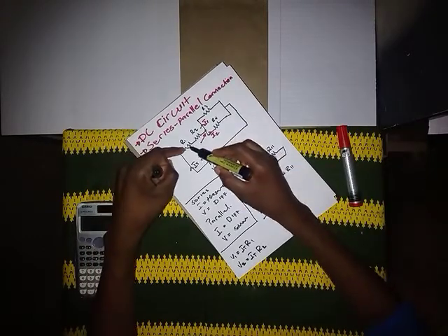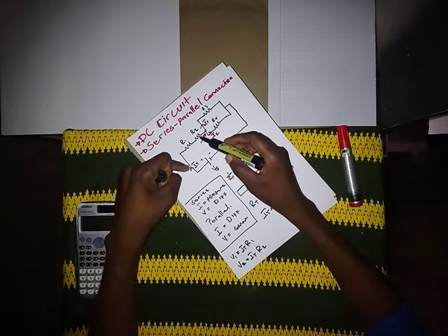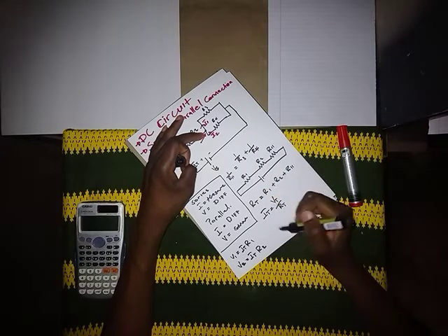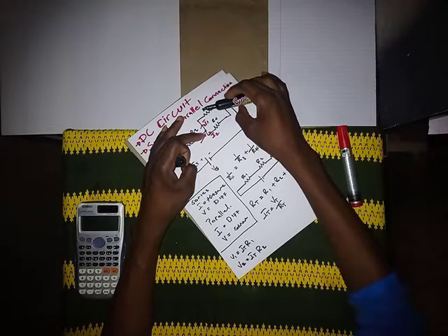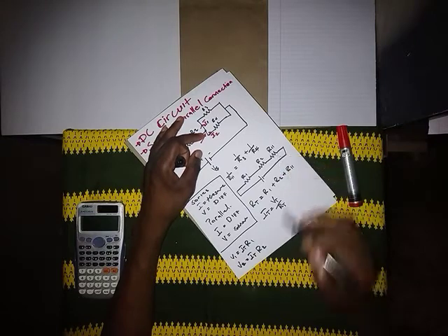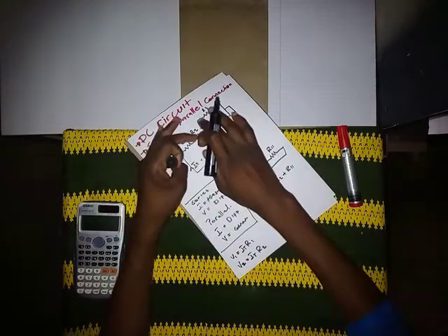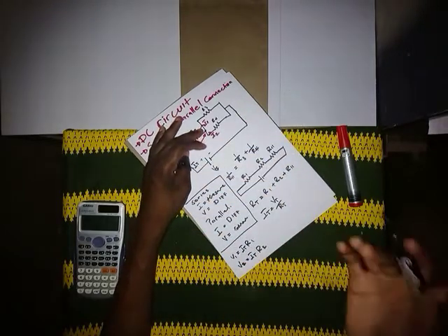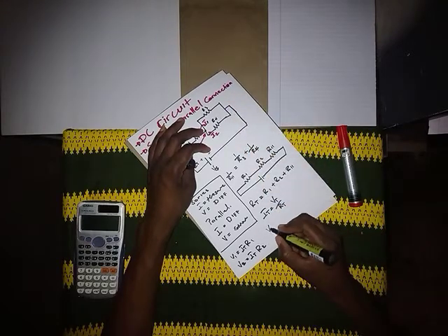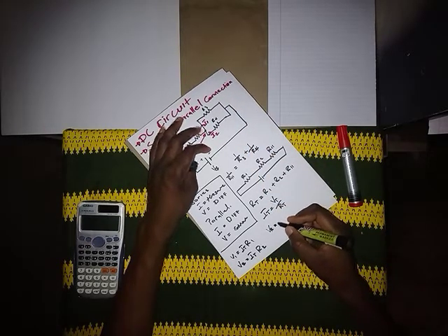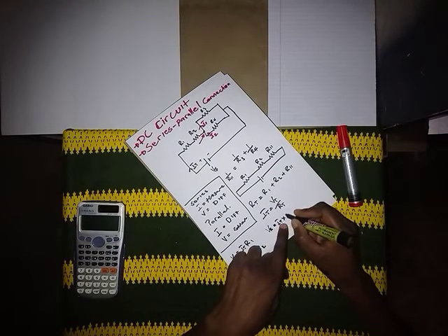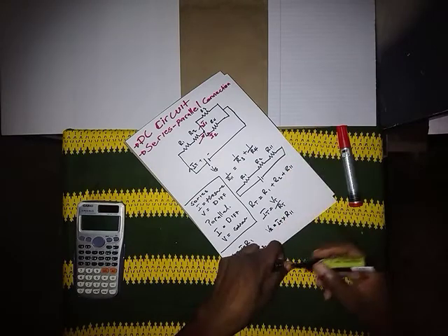So now we have the voltage here and we have the voltage here, which is calculated using the I total. We can simply put it into this form. We know that in a parallel circuit, the voltages are the same. So we can simply calculate the voltage here, because the current that is splitting here, the combination of both of them, is going to give us the total current. So we can use V, let's say VR4 or V parallel. We can use IT times R parallel, which is this one.